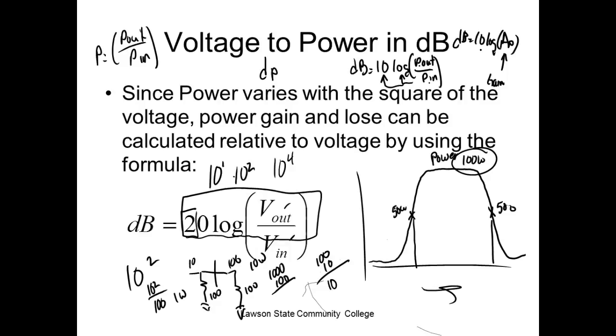But on this side, those windings have 300 ohms of impedance. The output, the secondary, has 50 ohms worth of impedance, so you're matching to a transformer. And they're not in there to give us voltage gain, they're not in there to give us power gain, it's in there to convert 300 ohm over to what? 50. And you could figure that out. I mean, so that's a really good point.